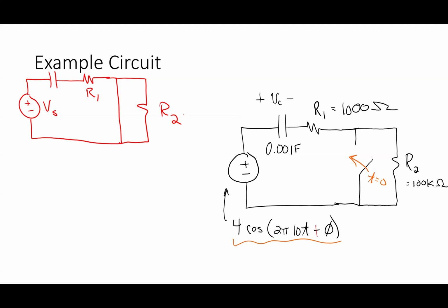So that's a memory device in your mind. The way I think about this, if you're in circuits 1, circuits 2, the way you should really think about that is if I do a KVL around this loop, Kirchhoff's voltage law, what's the sum of the voltages around a loop? Always 0, right? So the sum of the voltages is 0 around that loop. So that means I have 0 equals I times R2. What does I have to be?